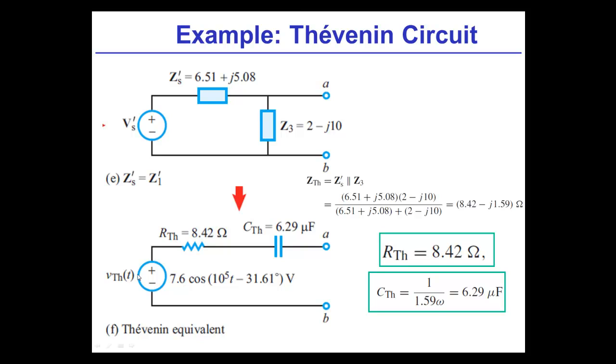So let's think about this. The Thevenin equivalent voltage has a magnitude, kept the same frequency, and then there's some weird phase shift that came from solving the problem. Right, okay? And the phase shift came from the fact that there was a complex impedance that had both a real part and an imaginary part. In other words, there were resistive elements and reactive elements that we were forming an equivalent circuit for. Oh, that's right. If you didn't have that, you wouldn't have gotten the phase shift. Maybe you'd have gotten this change, but not that. Right. Okay, that's perfect. And then, of course, the Thevenin impedance has a real part and a capacitance, and because we can tell whether it's a minus or a plus, we know whether this is a series capacitance or a series inductance. Exactly. This is pretty cool.